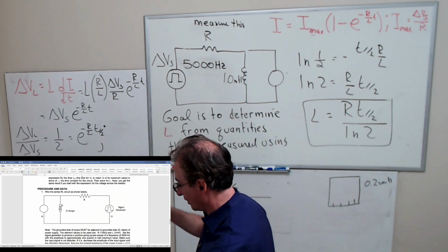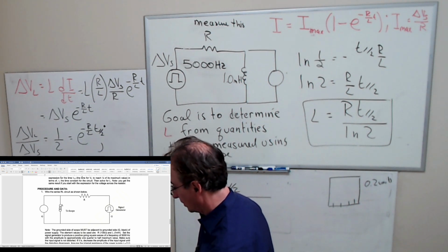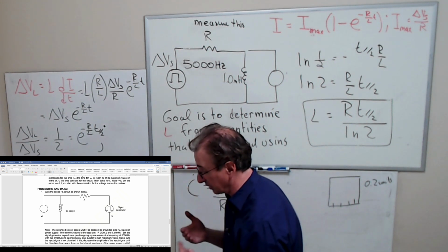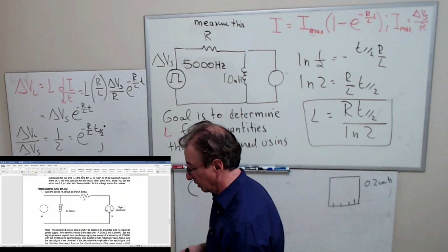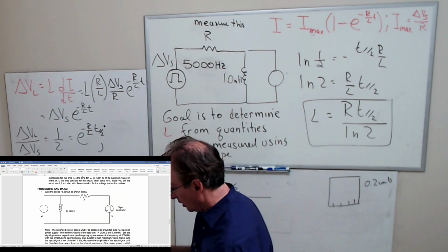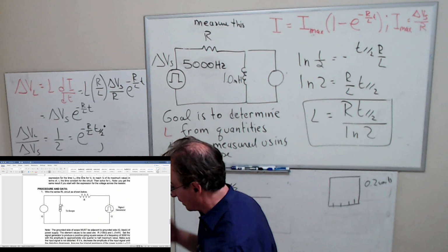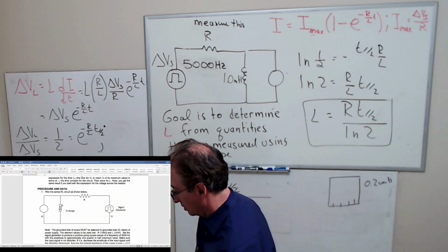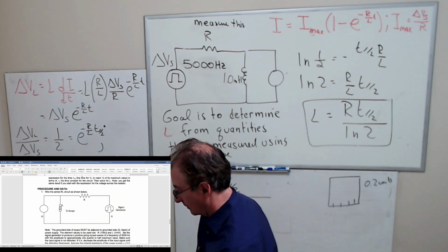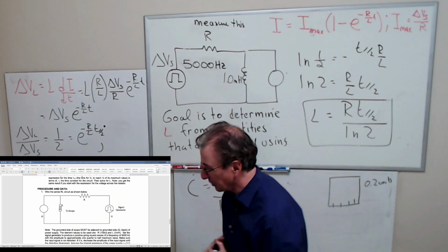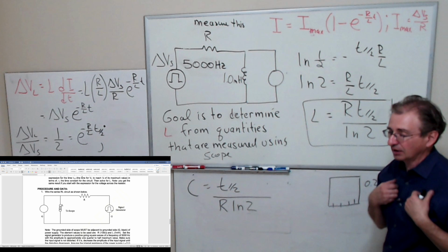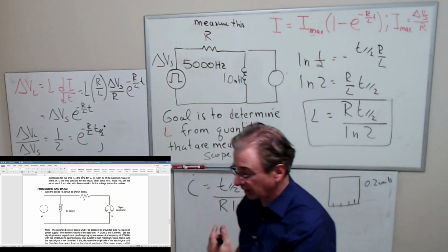You take the 0.1 units and multiply by the scale, whether you're measuring voltage or time. In this case, you're measuring time. You're not really measuring voltage. 0.1 times the time scale gives you the uncertainty. Does that make sense? Yeah, I wouldn't go below that. Some people try to go below that and get the extra digit. I'm not comfortable with that because of the width of the trace.